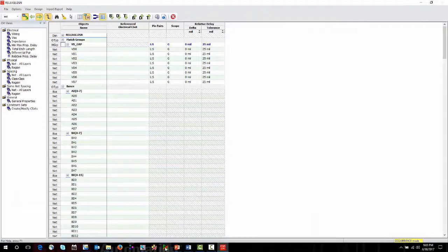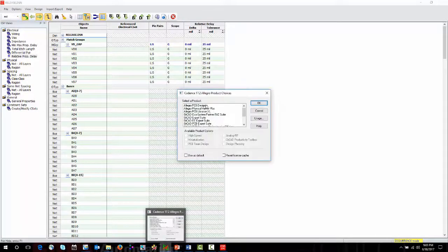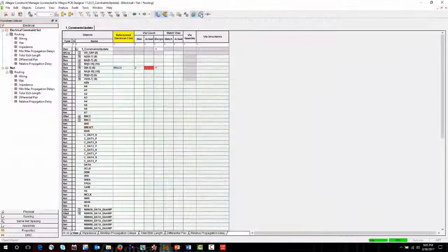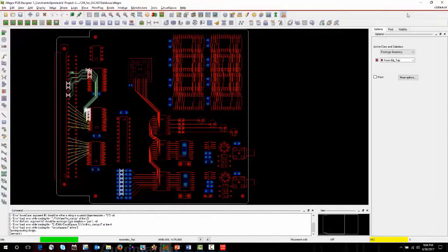One thing I didn't really mention, let's go back there for just a moment and look in the Constraint Manager. You'll notice that some of our nets are XNets. That means they are one signal path that traverses a discrete passive component. OrCAD does not usually recognize these, but we can actually back annotate them into OrCAD.